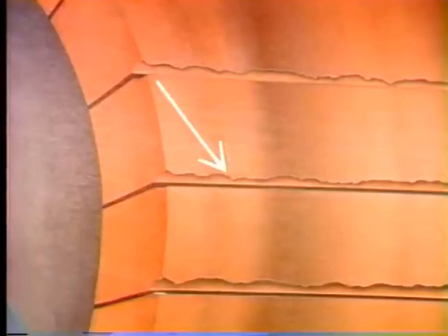What we're going to look at next is an indication of copper drag. These copper flakes that you see at the trailing edge of the commutator could be an early warning of trouble. If enough flakes accumulate, they'll close the space between the commutator segments, and then you've got flashover to deal with. We'll say more about flashover in a minute. But before we do, let's go over what causes copper drag.